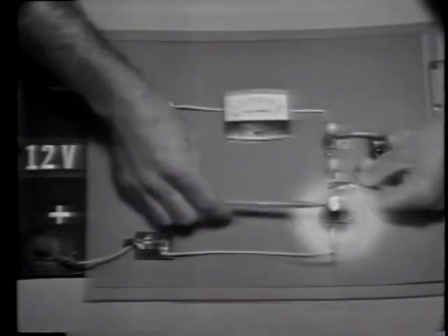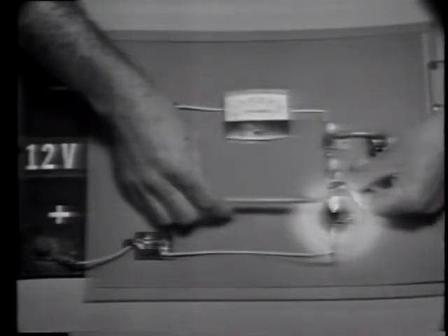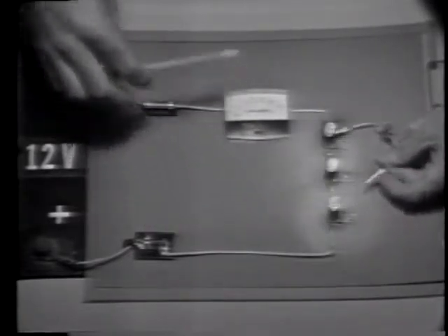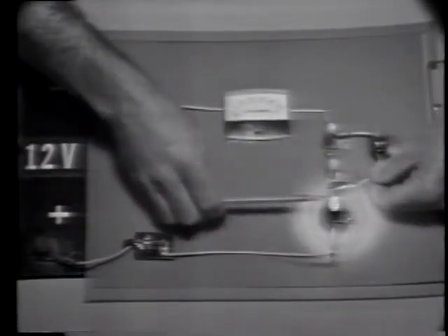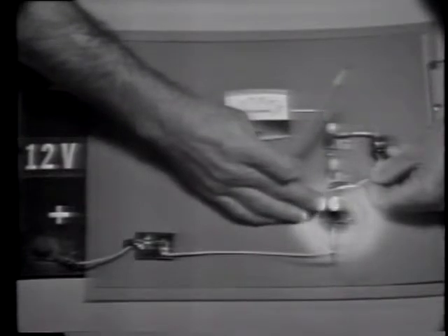Now, let's load the circuit. When I make this final connection, down here, watch for an increase in current. Okay, there it is. You can see that this bulb is brighter. There's more current through it. Well, let's look at it again. There's the circuit unloaded. When I load it, current here increases. And according to Ohm's law, if the current here increases, the voltage drop will increase.